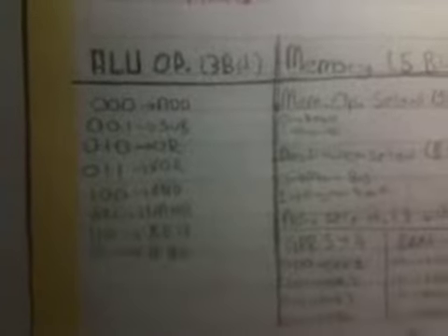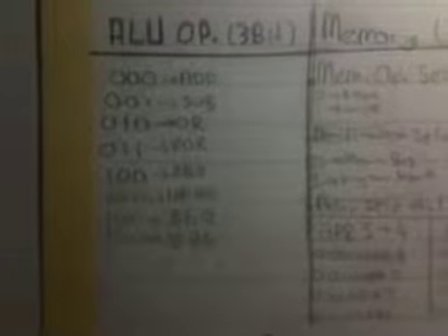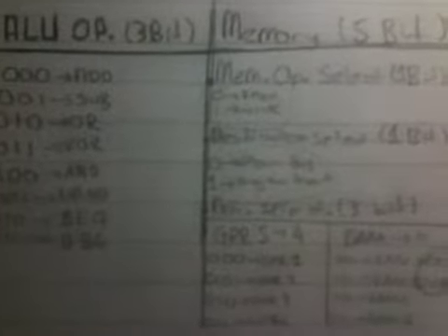Now, let's get started with these operations. First off, we have this ALU operation selector, which is 3 bits, and as you can see on the screen right now, 0 add, 1 subtract, 2 or, 3 XOR, 4 and, 5 NAND, 6 branch if A equals B, 7 branch if A bigger than B. And these are pretty straightforward and pretty much everyone else knows them.